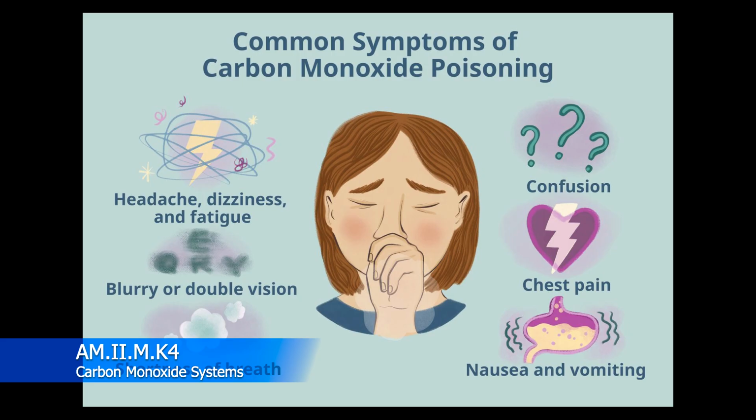Now, where that starts to factor into aviation is that you'll have inefficient combustion going through your muffler, and that muffler will have a crack in it, and that crack will then leak exhaust into the airplane. A big part of that exhaust is carbon monoxide, and it starts to accumulate inside of the airplane, and then boom, next thing you know, you're dying, and you don't even know it.